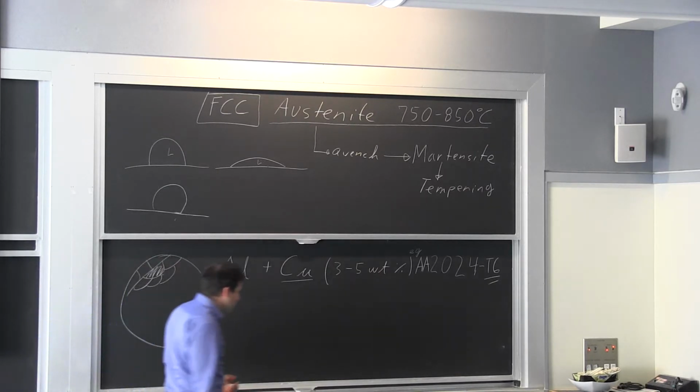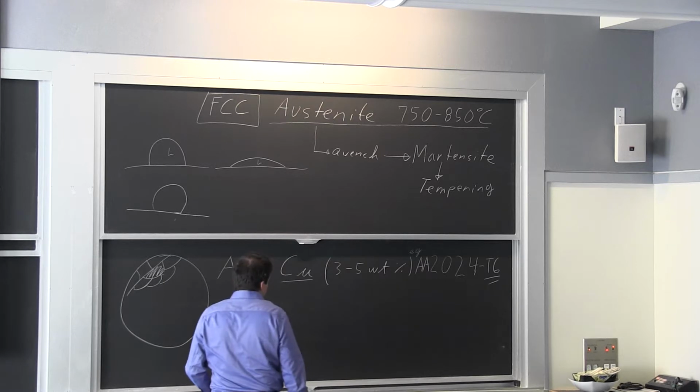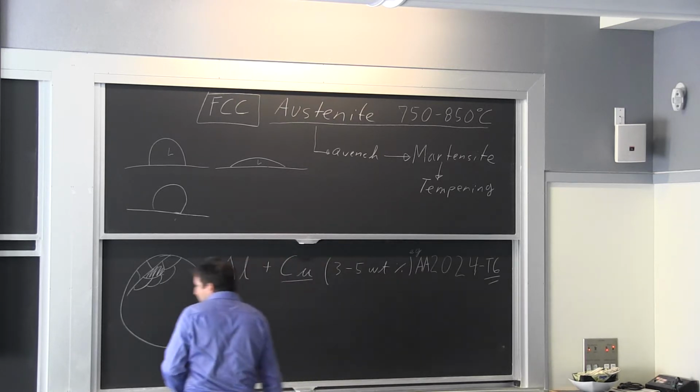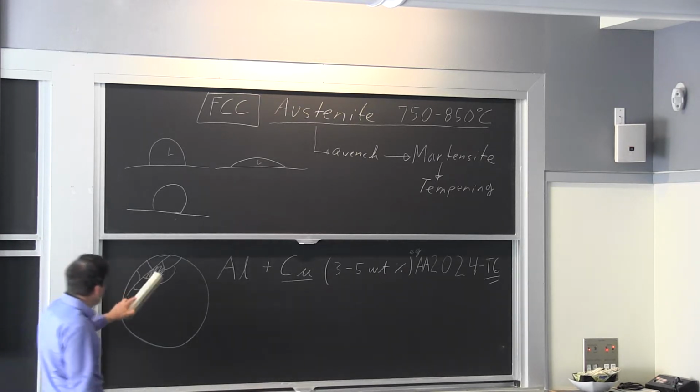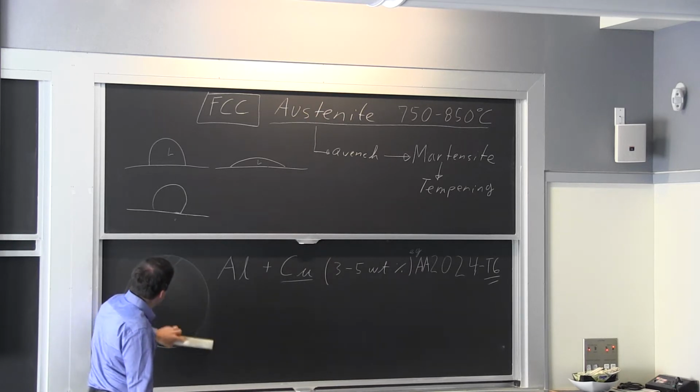So the quenching is called quenching as well, but it's very different than in steel, because when you quench, all you do is freeze the structure that was the high temperature structure. There's no other phase, there's no martensite forming, so you have one phase that just has extra copper in the microstructure. So we're avoiding, this is the one thing we really just don't want to have.